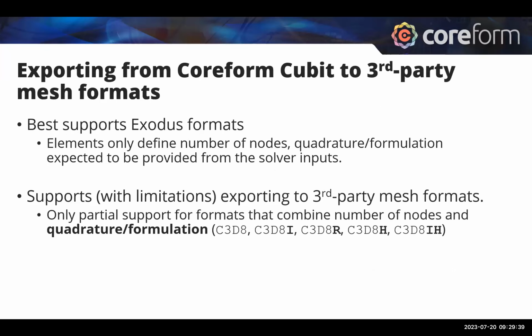And then a final note here on exporting from Coreform Cubit to third-party formats. As I mentioned, Cubit does best support the Exodus formats, but in Exodus, elements only define the number of nodes. All the decisions about the quadrature or special formulation ideas like hybrid formulations, selective deviatoric quadrature schemes, reduced integration, full integration, those are expected to be provided by the solver.